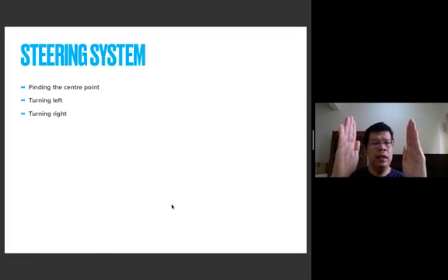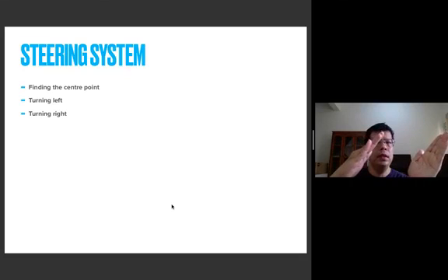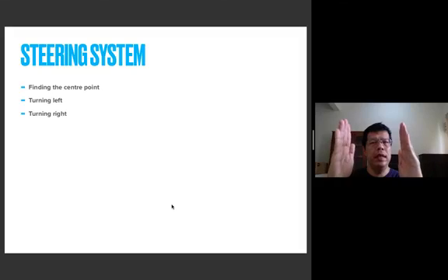Okay, so let's say, for instance, when you first start up the EV3 program, the EV3 doesn't know where the wheels are supposed to be. So you need to find a way to make the wheels point straight forward. One of the ways of doing this is turning as far as possible to one direction, and then turning back a certain number of degrees so that it points straight forward.